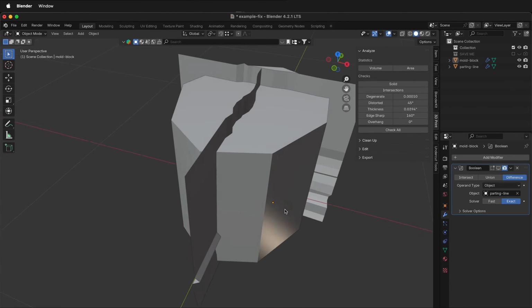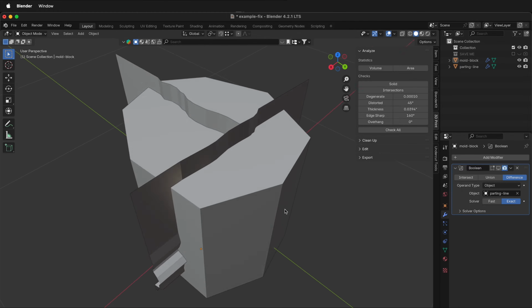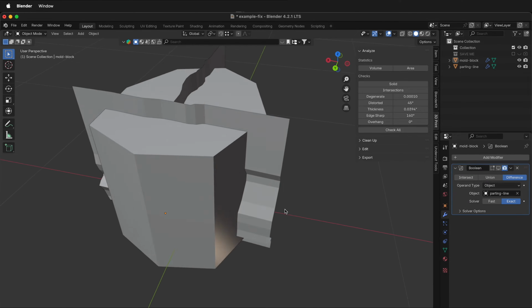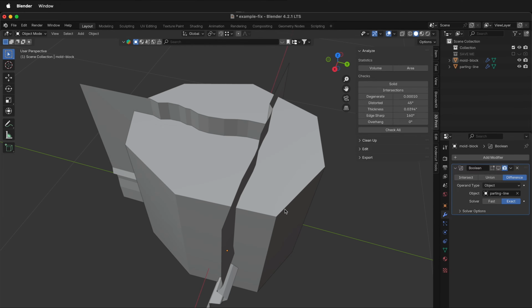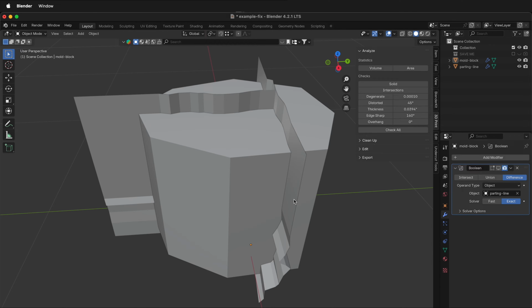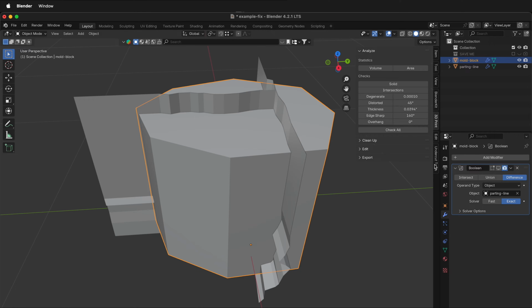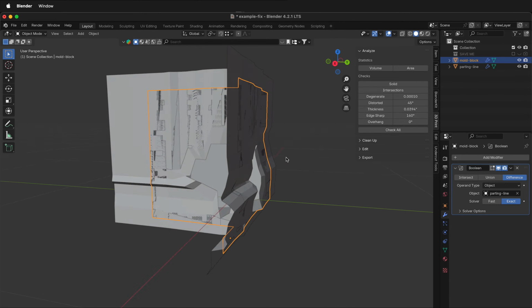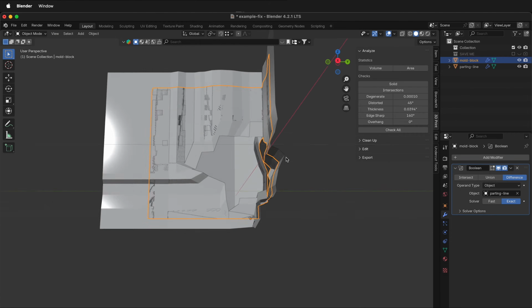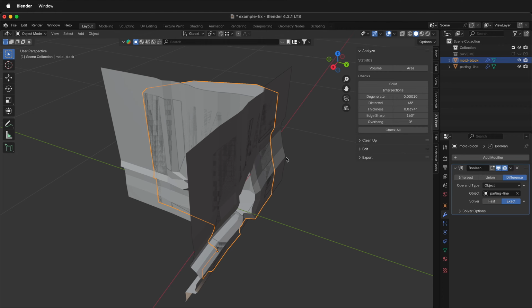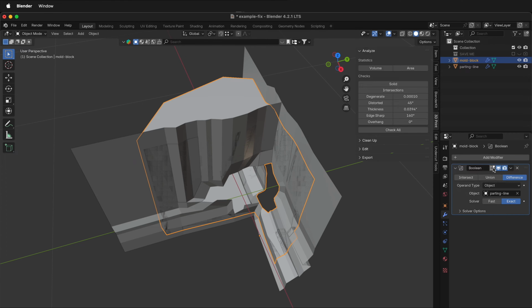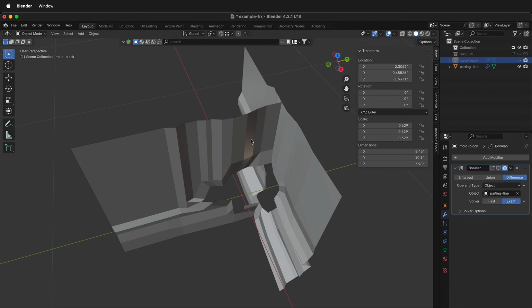In this Blender tutorial, I'm going to show you some problems and some potential fixes for when you're making parting lines for a 3D print slip cast mold. The problem comes in when you try to Boolean and then nothing seems to work. For example, here I have a mold block and a parting line. If I select the mold block and then activate the Boolean, suddenly most of it goes away and everything doesn't work right. For now, I'll hide the Boolean and hide the mold block.